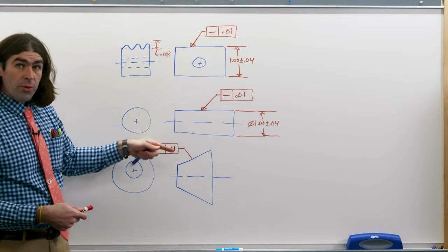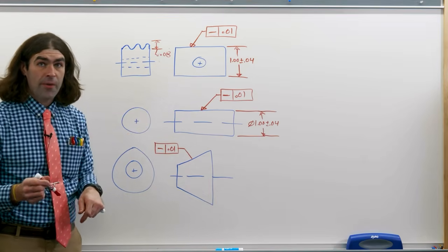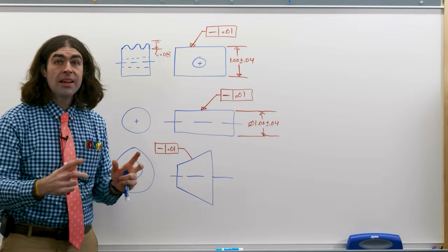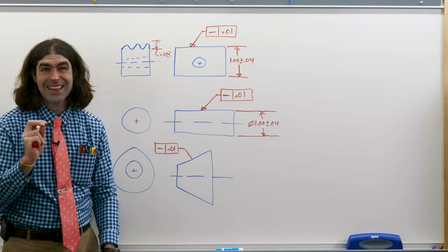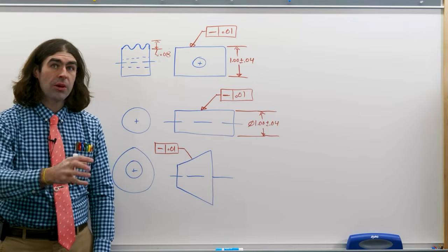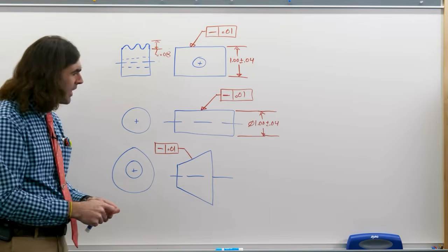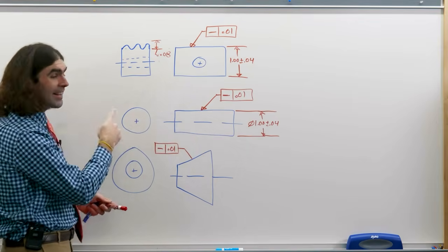It applies all the way around the cylinder, but only individual line elements. So you can check one, spin it, check again. You could even shim the part to a degree and check. You only care that the individual line elements are straight. There's no relationship to any of the other line elements on the part. And again, it only applies in this direction, not in this direction.